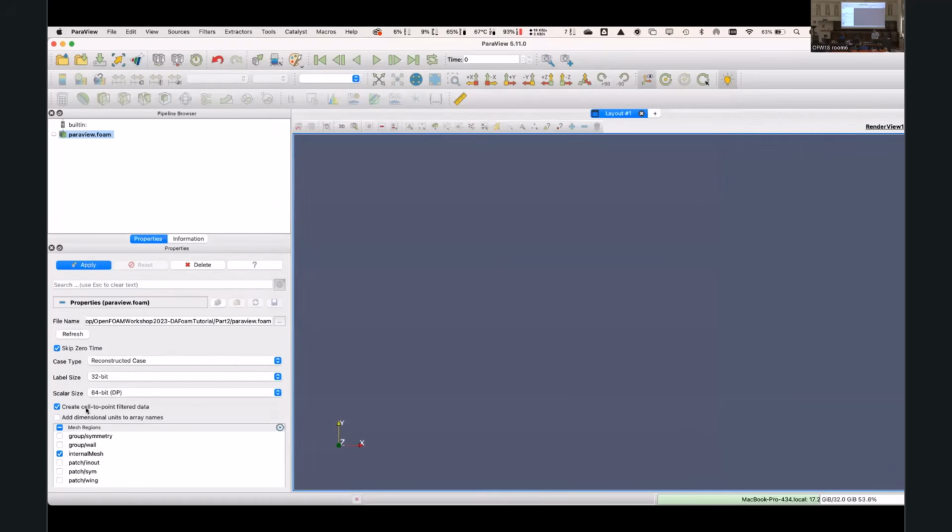Now, DAFoam will automatically renumber all of the iterations as time steps in the OpenFOAM case. So it'll automatically load as 1, 2, 3, 4, all the way to your number of iterations. In this case, it ran for 100 iterations, so we should see 100 times. I do have it as decomposed, so I'll open it in its parallel state.